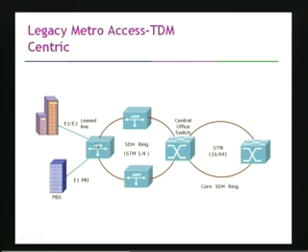From these SDH add drop multiplexers, typically the ADMs will have E1 lines or E3 lines as their inputs, and the SDH or SONET as the output. So, you can then drop an E1 or E3 based leased line to an enterprise for providing broadband services, or for providing voice connectivity, you can give an E1 PRI line which can be connected to an EPABX of an enterprise.